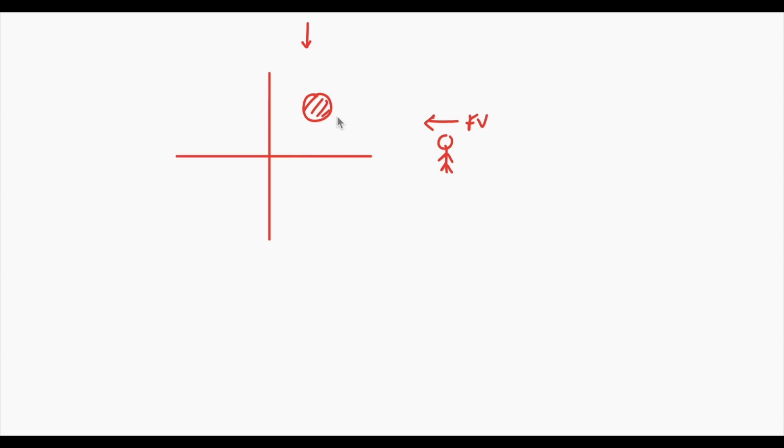Now when you look at the object to draw its front view, the front view will be projected on the vertical plane which is behind the object. We know this intersection is nothing but our xy line. So when the front view is drawn, it is going to appear above the xy line.